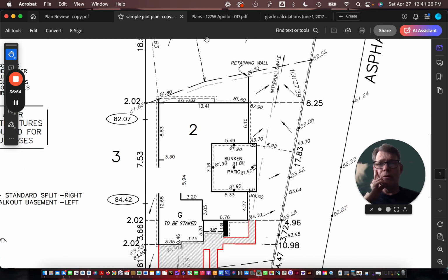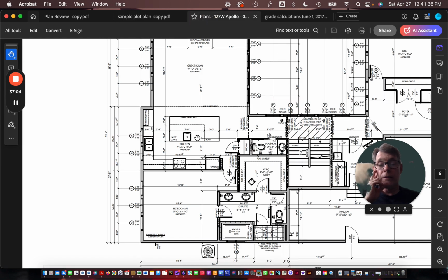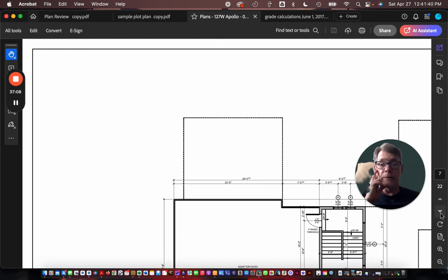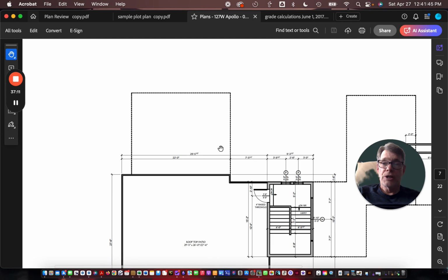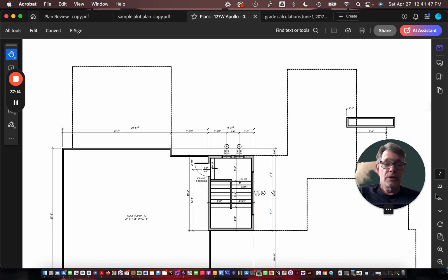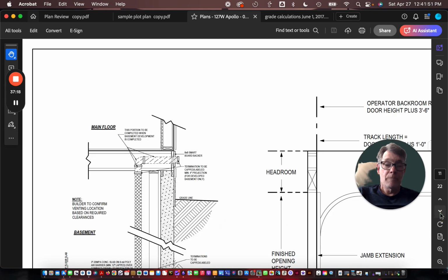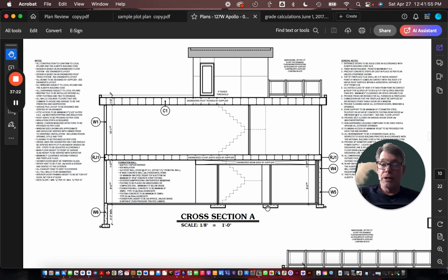So all we want to do is make sure that we have a foundation structure that goes below the frost. Otherwise, we're in trouble. We might see clues about that in the drawings, and I realize this drawing set is 22 pages. By the way, if your builder is not producing 20-odd pages of drawings for your house, pay attention to that, because it's pretty hard to do.